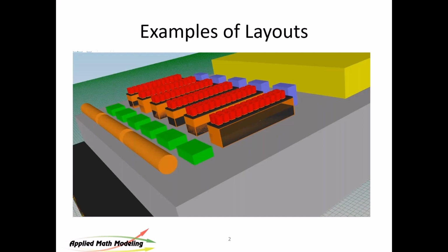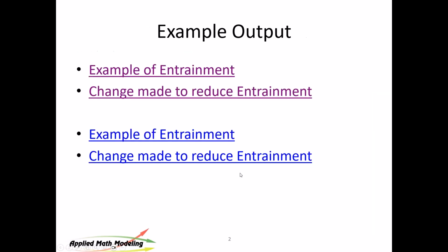Another example here. Now, in this case, there's some structures in front of these heat exchangers. I think the goal here was to get these further back on the roof so that they're not being contaminated. This is the same variation of the same design I showed you before. The generators are down here and they're blowing heat up over this edge. It's okay to have other stuff up there, but let's keep the heat exchangers as far away from that hot air as we can get.